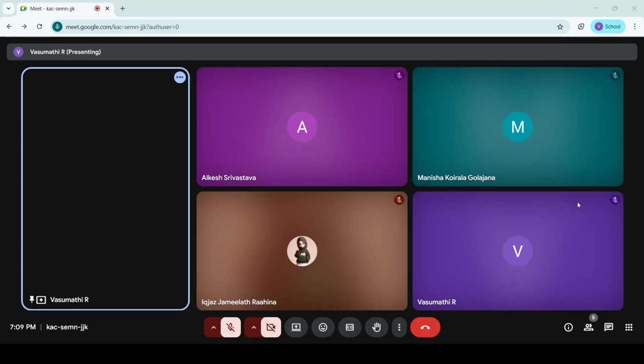Okay. So when you are asked to find the transfer function of a given electrical system, try to do KVL, or sometimes if the circuit is straight away a parallel circuit with two different nodes or a single partition, you can straight away use the voltage divider rule instead of calculating for each node.